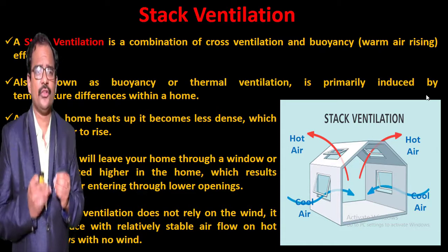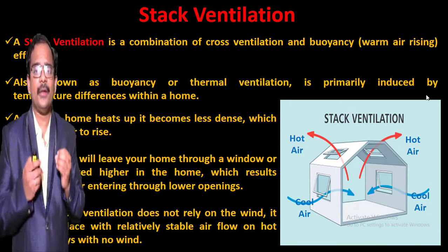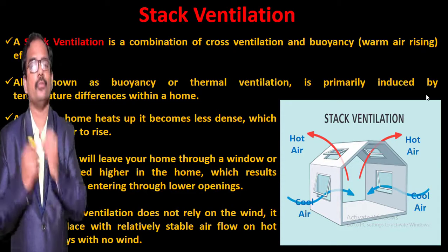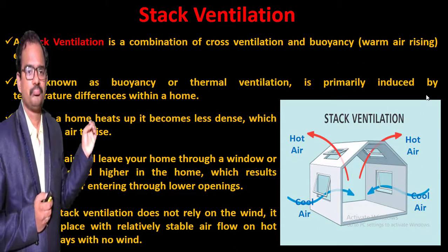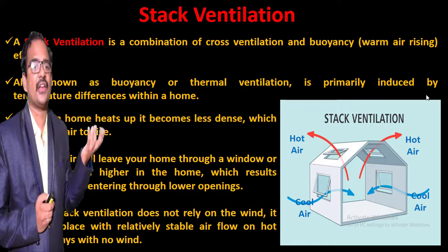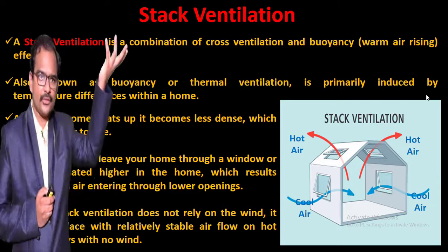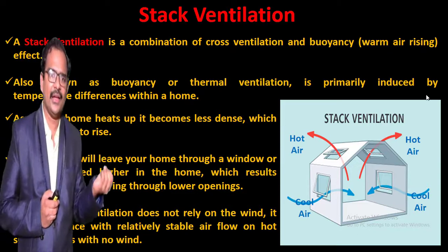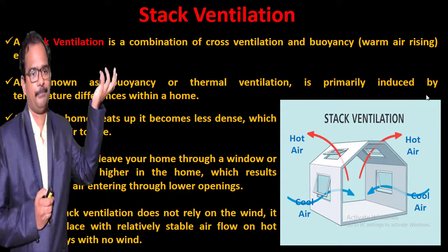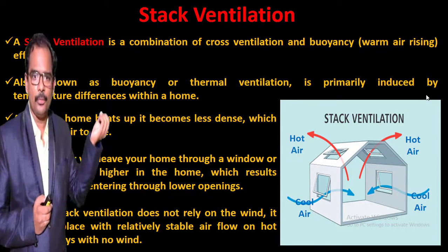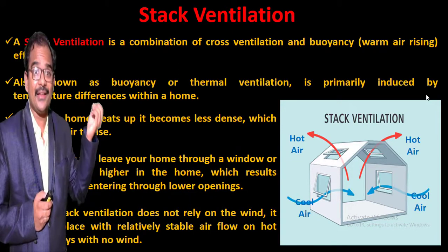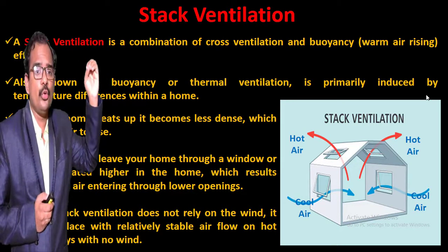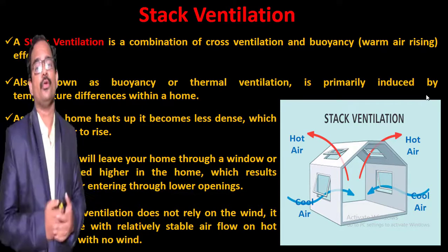And this is also known as buoyancy or thermal ventilation, and it is primarily induced by temperature difference within a home, right? So as air in a room heats up, it becomes less dense, which causes the air to rise. It's a basic principle. Whenever you heat the air, automatically the density of the air will decrease and it becomes light and it will move upwards. And this warm air will leave your home through a window or opening located higher in the home or a room or a closed space, which results in cool fresh air entering through lower windows.